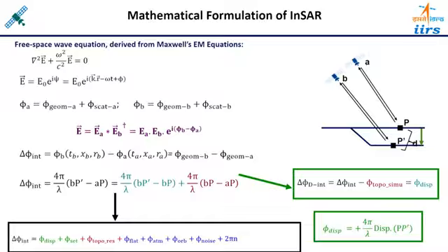Continuously people are measuring those tides also. Those data sets you can use to understand that this much tide is developed in this particular region, and hence this much contribution is there from the solid earth tide in the interferometric phase. Similarly, the topographic phase: because of hilly regions, and land going beyond the geoid or the spheroid, that height is nothing but the topography. So because of the topography also, some contribution to the phase difference is generated.